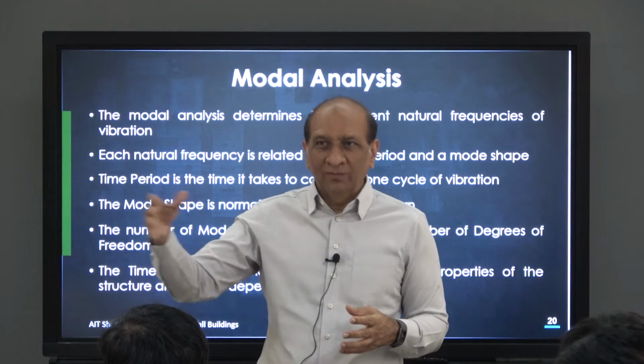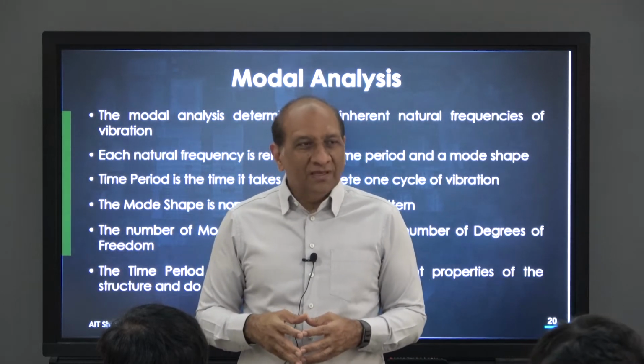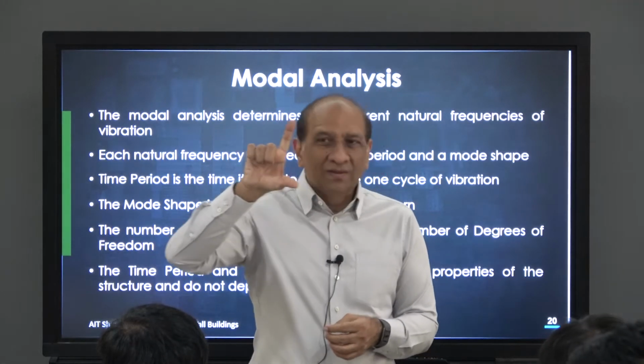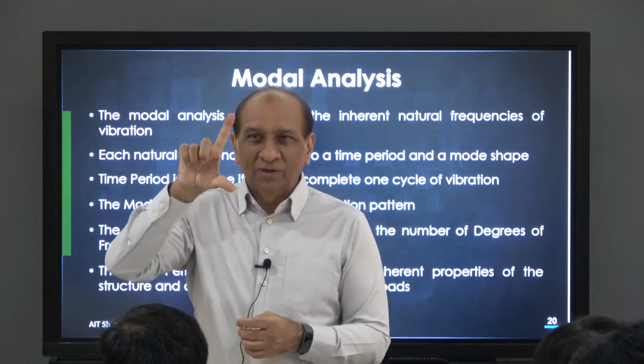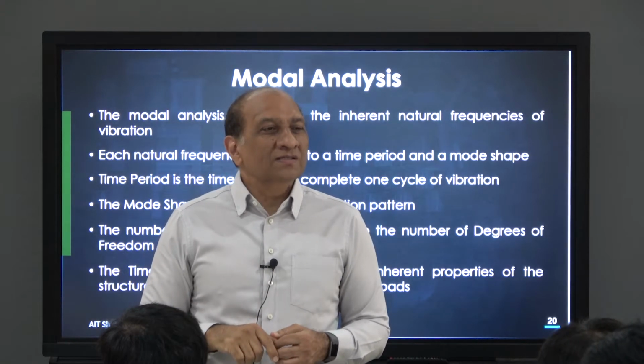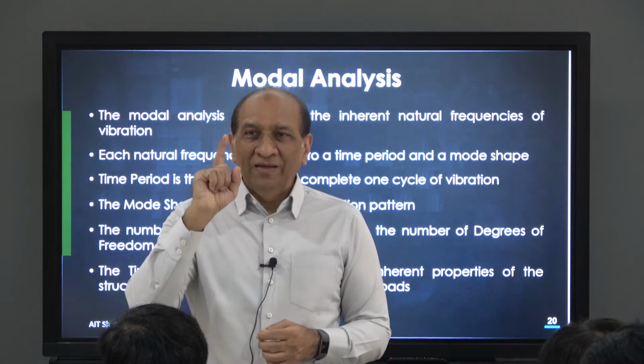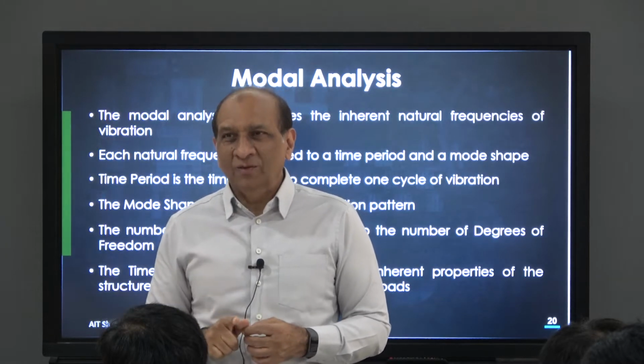We say first mode, second mode, third mode. However, if you put a small antenna on the building and model it, you will see that the first several modes will actually be the modes of that antenna, not of the building.